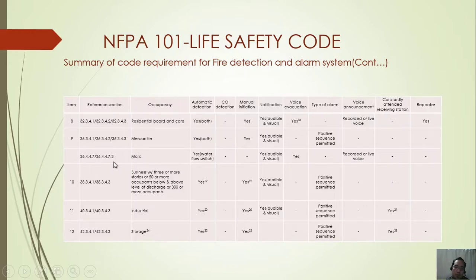For malls, yes, no requirements for fire detection, only water flow switch, supervision. Pull station can be excluded once you have sprinklers in malls. There's no requirement. Notification, audible and visual.